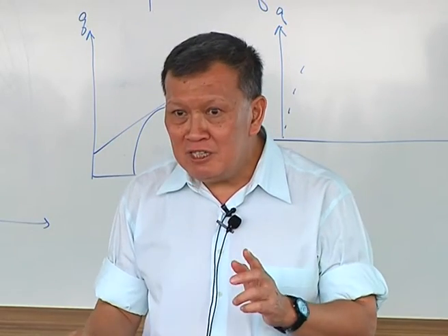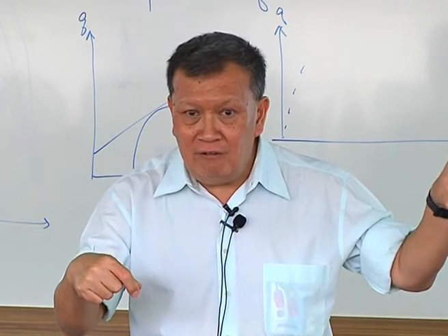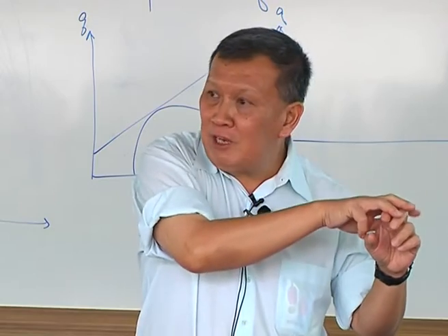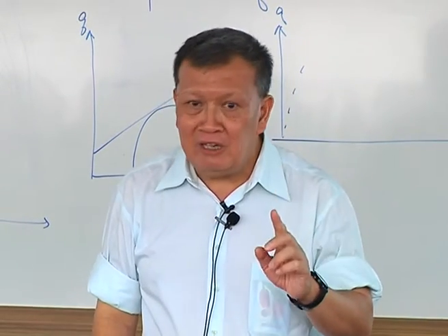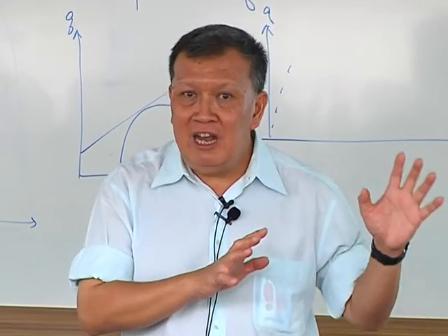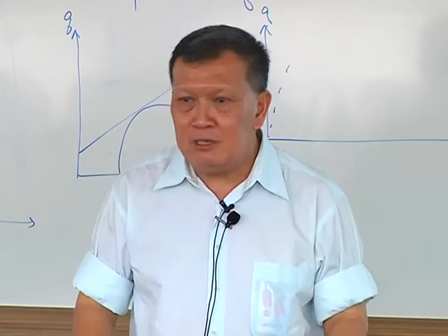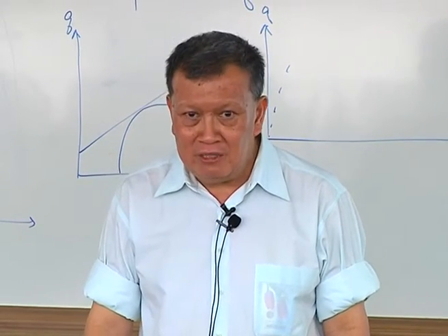So what Plaxis is doing is to take the angle of friction, use Jaky's relationship to deduce the K0 value, and fit an elliptical envelope based on that K0 value. So Plaxis is matching K0 to what is Jaky's prediction. Is that all right? Based on the angle of friction.